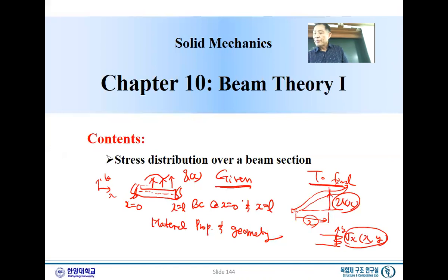And now, to derive this equation, we first assume there is a moment M as just a function of x. Forget about everything, forget the distributed load and everything. We just want a moment M(x) as a function of some angle. When it deforms, it will have a certain angle, right?